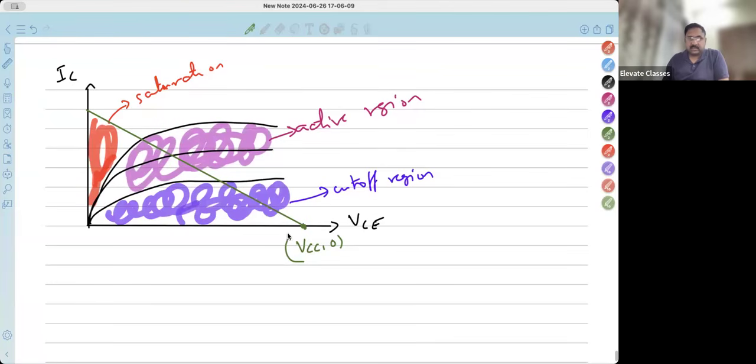Okay, I'm just briefly giving you an idea of what the load line is. Then somewhere over here will be the Q point. What is the Q point? Q point is just the value of VC, IC, just an X, Y coordinate. VC is the output voltage. IC is the output current. Next, what is the maximum saturation current? Does anyone remember this value? What was the value of IC saturation? This value is VCC upon RC.